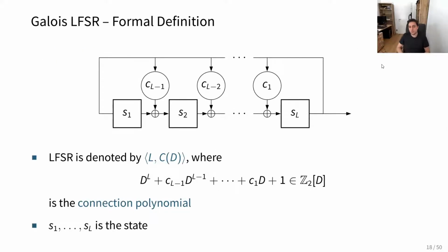And now we come back to our LFSR. We try to connect this polynomial somehow with our LFSR. Note that we have a slightly different graphic here. We don't have this Fibonacci LFSR anymore, but instead we have this Galois LFSR. Again, they are equivalent, so one can be transformed into the other, and the properties are the same. It's just a different way to represent the LFSR.